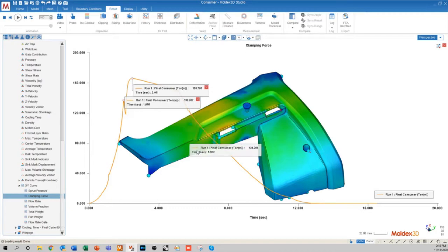As the material cools, it will shrink, and as it shrinks, the clamping force will gradually decrease. Eventually your clamping force should get all the way to 0 as your material shrinks off of the mold. And that is something that we can simulate, as you can see here. So the most important thing is to make sure that you're looking at the clamping force in the packing stage, and then we can accurately designate which machine, or what size machine, we should be putting this part onto.